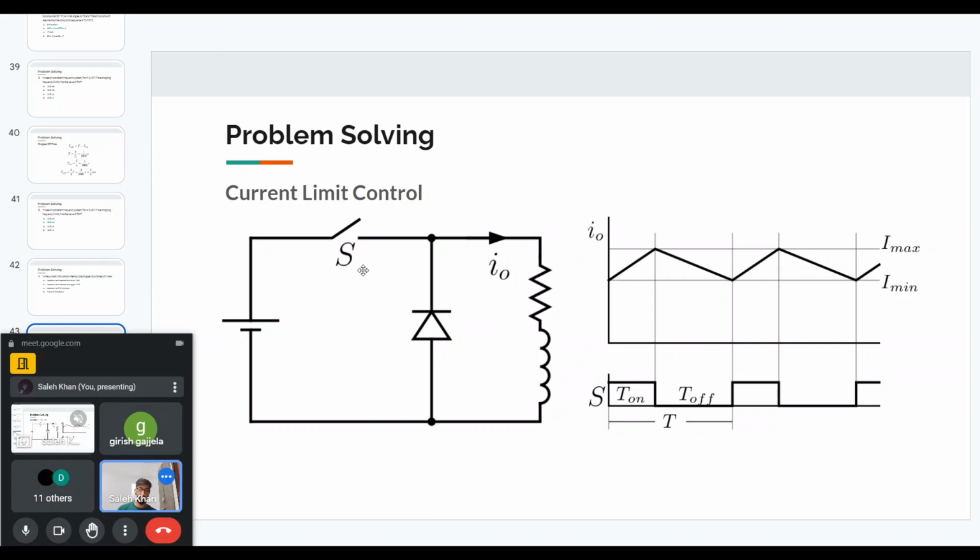And basically we will use thyristor only in case of high power applications, because in low power applications thyristor is not recommended, because the switching frequency is limited. We cannot go to very high switching frequencies, and that means the filter L and C components will be quite large.